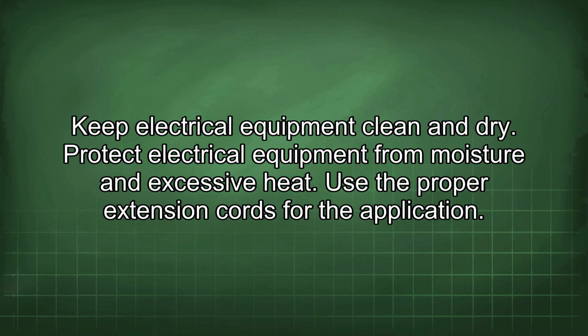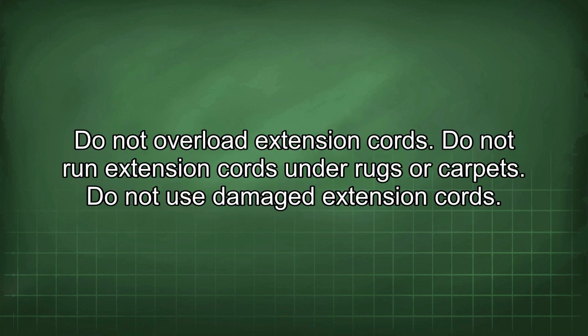Use the proper extension cords for the application. Do not overload extension cords. Do not run extension cords under rugs or carpets. Do not use damaged extension cords.